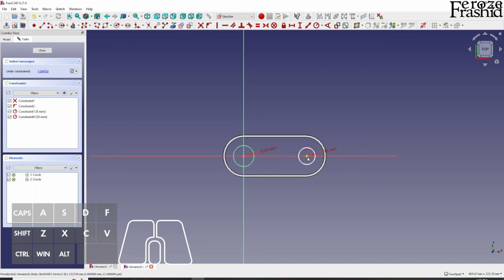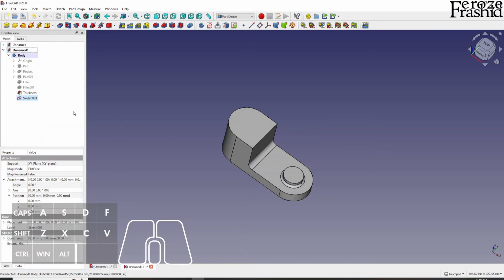And then the distance between them will be 60 millimeter. I feel like it's a little repetitive to enter the 60 millimeter every time. That's where the spreadsheet comes in, makes it simple. But again, we could reference it with one of the sketches, but I just didn't want to do that. I want to keep them separated and independent. Now select pocket.